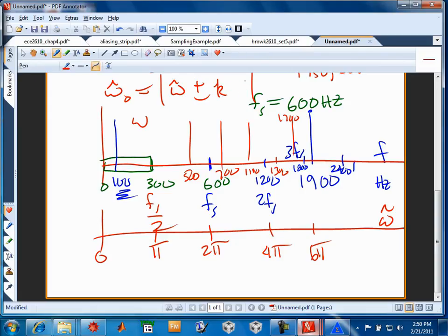Not that, but 2 pi. So we could have done it that way too. Same idea. It's just how you convert, whether you want to go to the discrete time first. I tend to like the analog frequency axis better just because I can relate to it physically better, as it's in hertz. The radians just seem to be more abstracted to me. I like the idea that I've got these harmonics of the sampling rate clock, and I think of the real sinusoidal frequencies that alias.